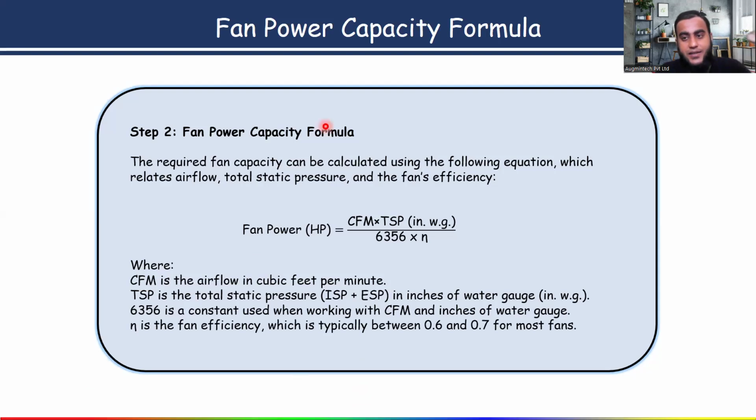Before starting the external static pressure by using the layout, these are important things which I want to discuss with you. So first, let me know if each and every step is clear. So simply, this is your formula in front of you. Now the question may be coming to your mind: sir, from where do we get the airflow value? Remember, for the airflow value, we have to do the heat load calculation. Simple. First of all, we have to perform the heat load calculation.